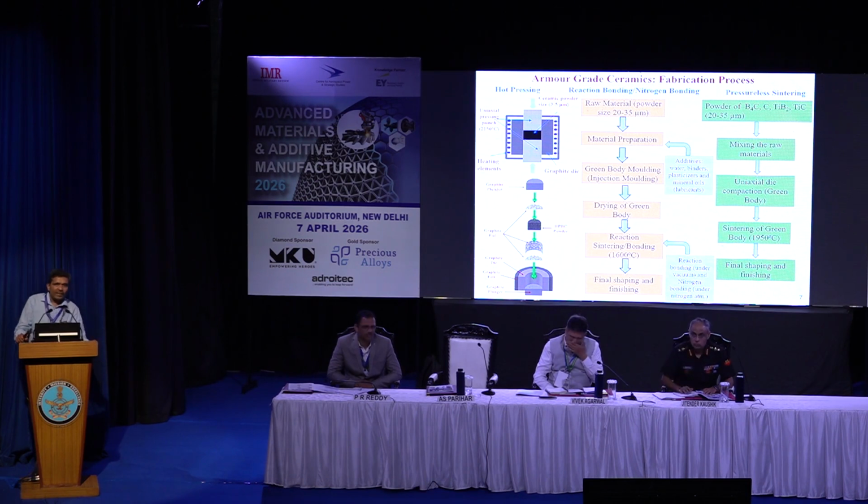And for the tile solution, the integration is extremely important, because there should be no gap. The integration also matters when we are using the backing composite, and the adhesive type will also be important, because after shot number 1, 2, and 3, the bullet is stopped in a specified area, but the stress wave, the shock wave generated in the entire structure of the plate, causes debonding even in tiles which seem to be okay.